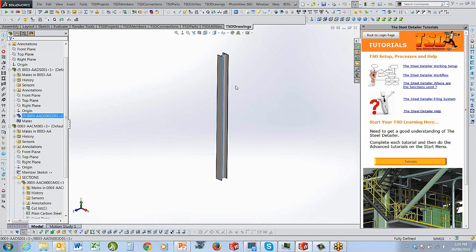We do not do arcs. There is a process for arcs. It's another sketch, but the member sketch is between the 2 points, 1 and 2, and there's always a straight line between the start and finish of an arc. The arc itself can have a member sketch as a radius in it, and you can use that in your driving sketch to snap the member sketch on. There's a tutorial we've got in the list that shows you how to do a curved member.